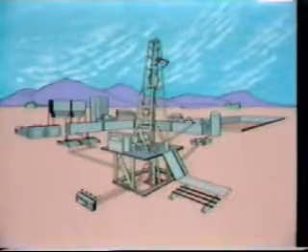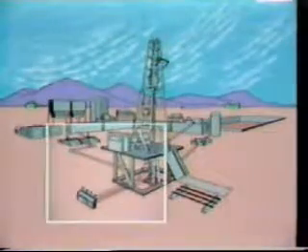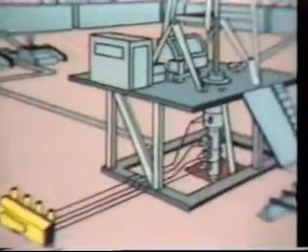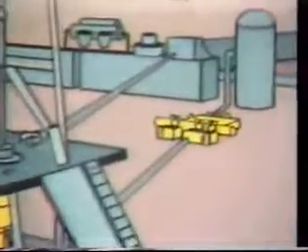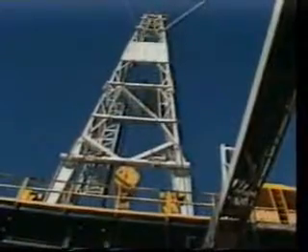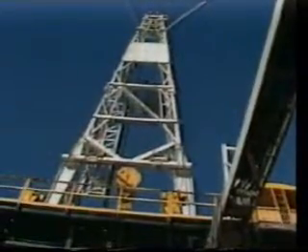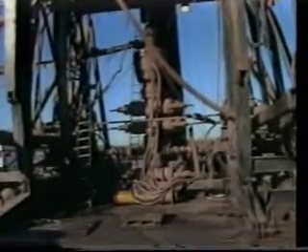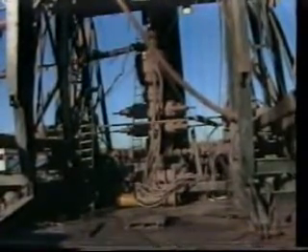Controlling subsurface pressure is the fourth basic function of the drilling system and is accomplished through the use of the accumulator, blowout preventers, and choke manifold. Although the drilling fluid is used to maintain hydrostatic pressure on the formations encountered by the drill bit, when the well unexpectedly kicks and subsurface flow occurs, the blowout prevention equipment is needed.